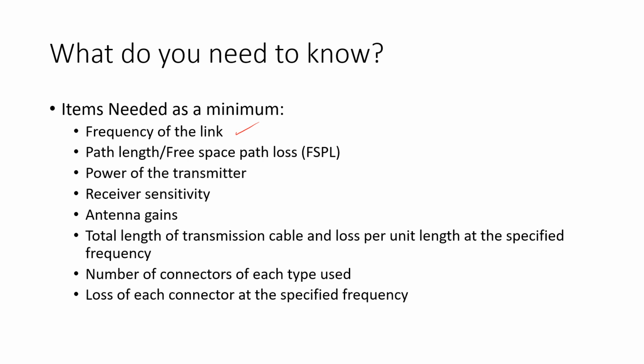Now, what you do need to be careful with is that whilst the receiver sensitivity might quote how low it can go and still work, it will not be working at the highest bit rate at that lowest sensitivity. In fact, it's quite hard to get data for most systems on the receiver sensitivity for the highest bit rates, but if you want the highest bit rates, you need to be operating a little bit above the receiver sensitivity value.